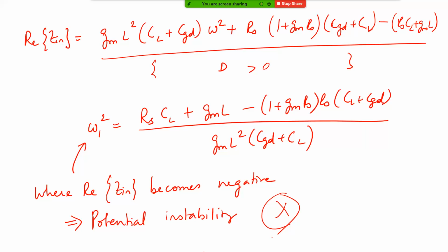And usually in the industry or even in research, whenever you do any LNA design or any RF amplifier design, you take a lot of pains to make sure that the LNA is stable. In the last class, I mentioned the K-delta stability factors, where there are multiple stability factors which you would have learnt in the microwave course. So any of them can be used. And typically, especially in the IC design industry, the first thing that people look at is the real part of the Zin.